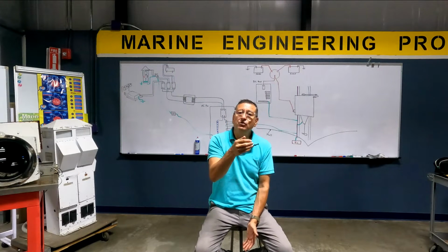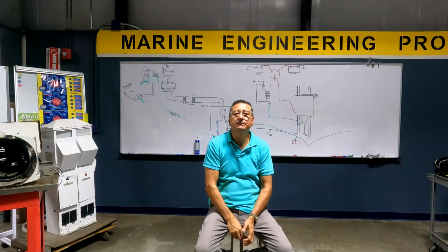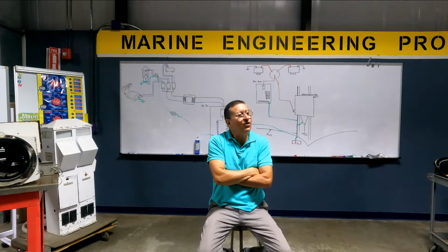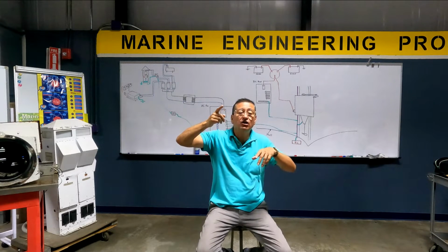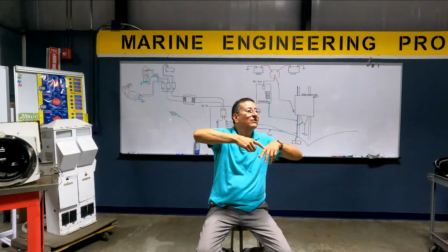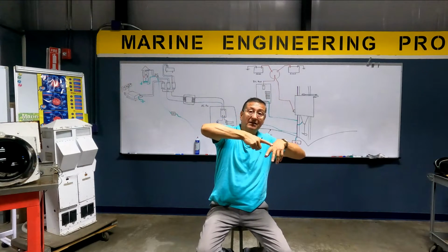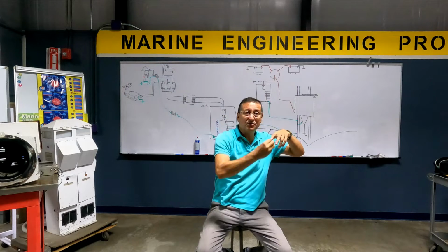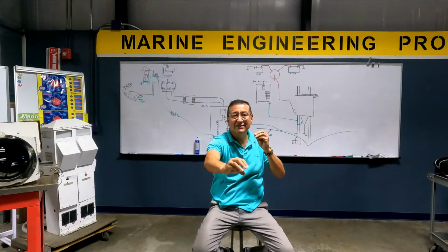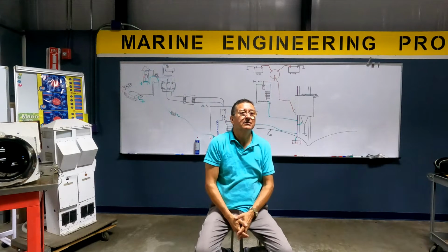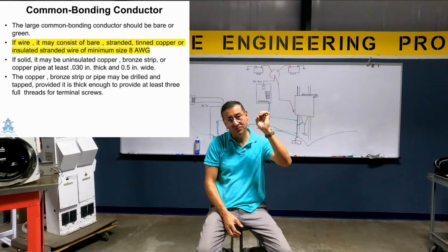Especially in medium boats and big boats, when you have an AC panel and a DC panel, you need to drain currents, and not only those static electricity currents. In some cases, what happens if one hot line is touching the metal of the frame of any equipment, the block of the engine? What happens with that hot line? It makes a short and the current is drained. In some cases, that bonding conductor, that grounding element, drains big currents. It's for a short period of time, but it's designed to drain. For that reason, there is the gauge of that wire.